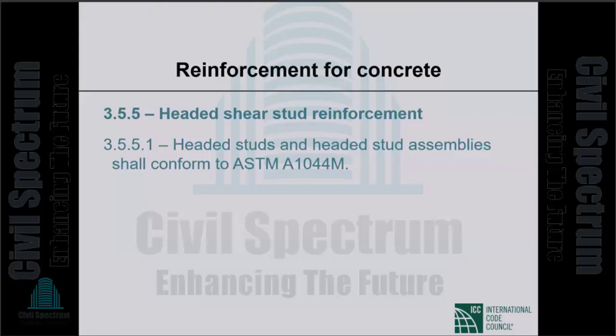In the design of that type of slabs, the critical thing is punching shear, two-way shear as opposed to one-way shear, commonly referred to as punching shear. When punching shear stress is beyond the punching shear stress carrying capacity of the concrete, we use punching shear reinforcement. And the most popular kind are now headed studs.